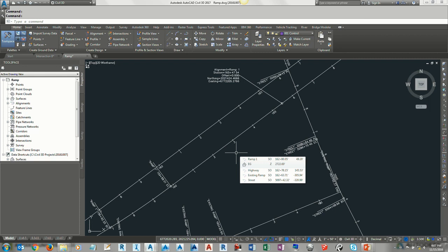Anyway, this is a problem, and what they did, since there's no good way, is you had to literally divide it, just like you would on construction, how it's going to get constructed. You would construct this one and then this one, so you basically end up making an alignment, and when you cut cross sections, you snap to that alignment from this side, and you start with the same alignment on the left side from this side. So you basically break the corridor when you're cutting material quantities, and you create sections and section views. You make an alignment. That's why they call that a match line.